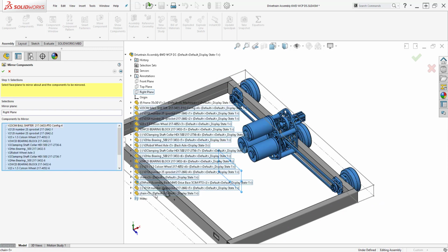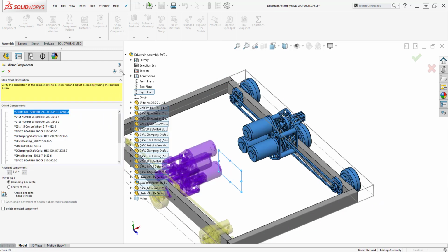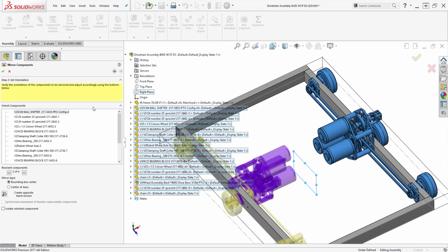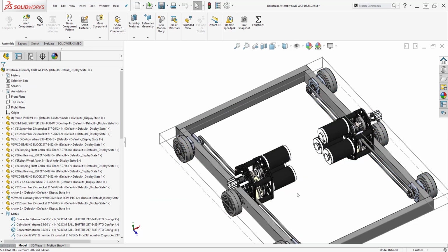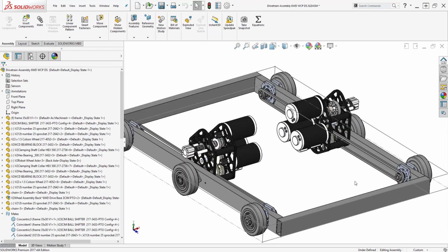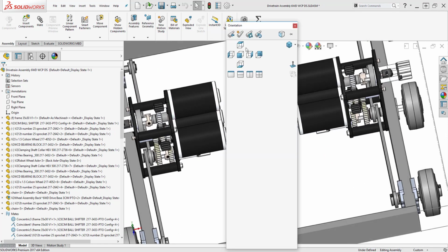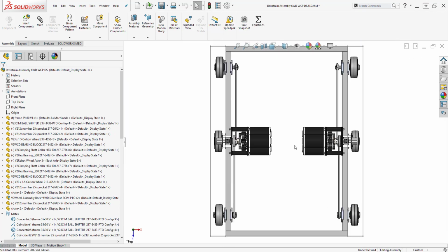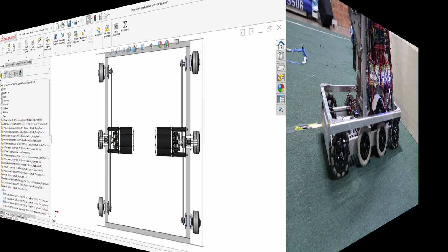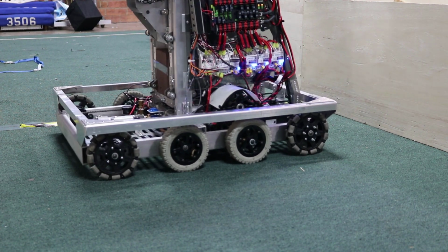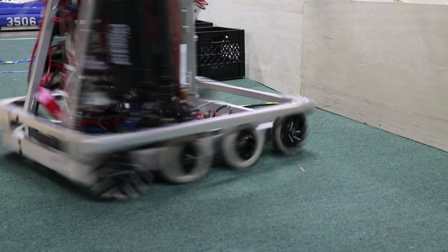Obviously, for an 8-wheel drive or 10-wheel drive, you have a little bit more work than the 6-wheel drive, but at this point you guys have already figured that out and you know what to do. The hardest thing here to do, guys, is the drop center. For an 8-wheel drive, the center is dropped on the 2 wheels. For a 10-wheel drive, the center is dropped once for the middle, and then the 4 wheels next to it have a smaller drop, followed by the outer wheels to make a smooth turning robot. If you want a no drop holonomic, flip the blocks upside down and just leave the middle dropped or raised the same height as the outside wheels.